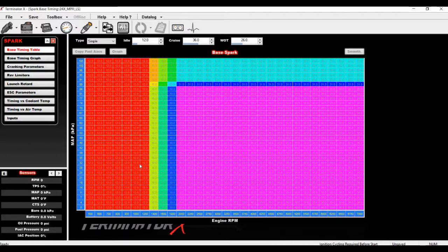When you are driving around and you're idling at 900 RPM and 12 degrees of ignition timing with your slightly larger than stock camshaft, and you go to pull away from a stoplight, especially, this is even worse than stick cars, you're going to rev up the engine a little bit to 1200 or so, and you're going to see a big drop in manifold pressure, and you're going to have exactly the same amount of timing at the same time.